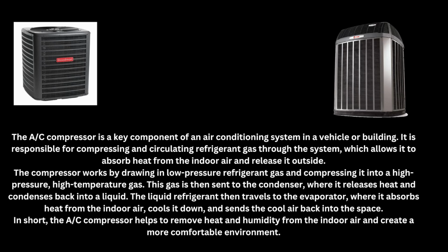What they have done is they have introduced moisture into the system, because with an HVAC system, its whole design is to bring temperatures down and remove humidity out of your home. That's why on a rainy, hot day, it's sticky, humid, 90% outside, but you go in your home and it's a comfortable 48 to 50 percent humidity, and that's why it feels comfortable.